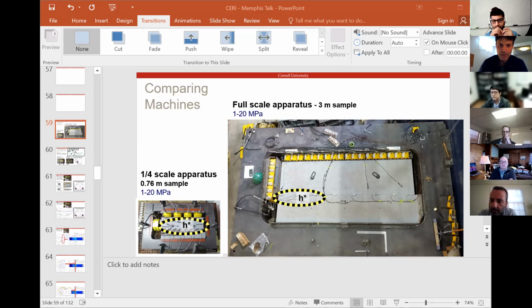And because of the asymmetry of the blocks and the asymmetry of the boundary conditions, we set up a stress state where it's very favorable to rupture about 2 meters down, and very unfavorable to rupture at the other end. It's really hard to measure, but not impossible actually. This is sort of what we think the initial shear stress distribution is. So we'll get a rupture.